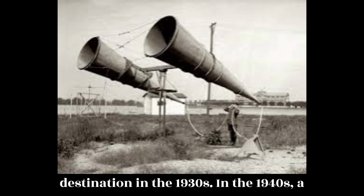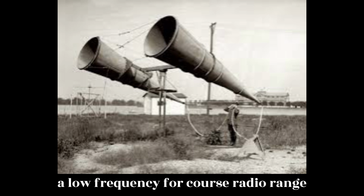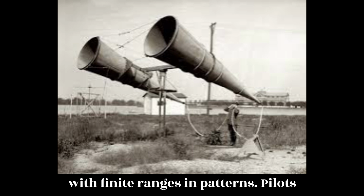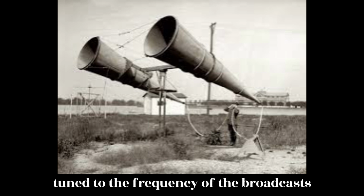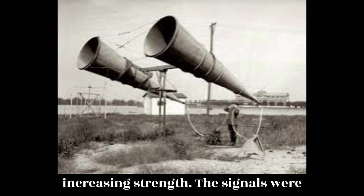In the 1930s and 1940s, a radio navigation system was used that was a low-frequency, four-course radio range system. Airports and selected navigation waypoints broadcast two Morse code signals with finite ranges and patterns. Pilots tuned to the frequency of the broadcasts and flew in an orientation pattern until both signals were received with increasing strength.